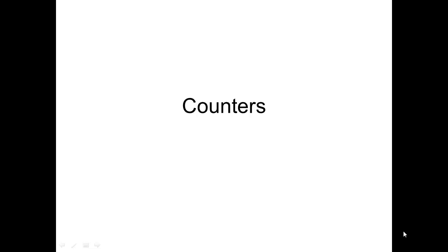This lesson we're going to discuss counter circuits, and counters are used in digital circuits to generate a count or a binary count, usually very logical, 0, 1, 2, 3, 4, 5, 6, 7 in binary. And we can do decade counters which only go from 0 to 9. We can do full 4-bit 0 to 15 counters. You can do any kind of counters you really want. We can even reset them in the middle.